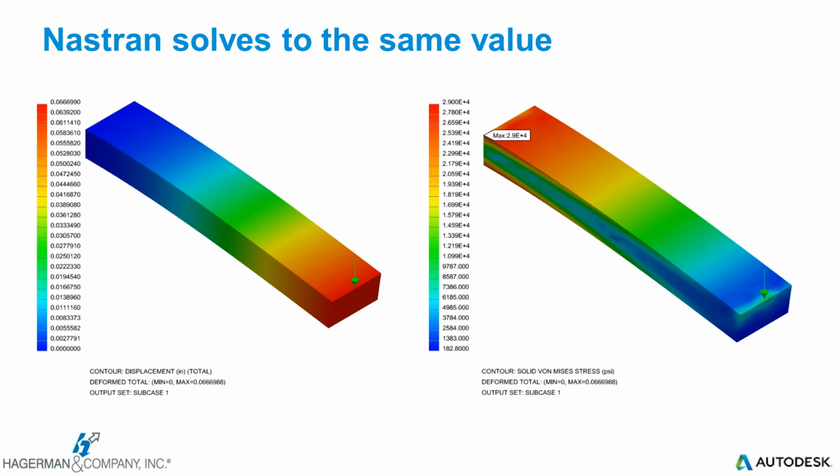One of the big advantages to Nastran In-CAD is that it can solve things with different types of meshing. So in our scenario, I simply went in and said, make this a solid block of material, use a solid mesh. If this were a very thin piece of material, or a U-shaped piece that was very uniform throughout its shape, I could have used a beam element and simplified that mesh even further. And that's one of the big advantages that we have using Nastran In-CAD versus using Inventor.